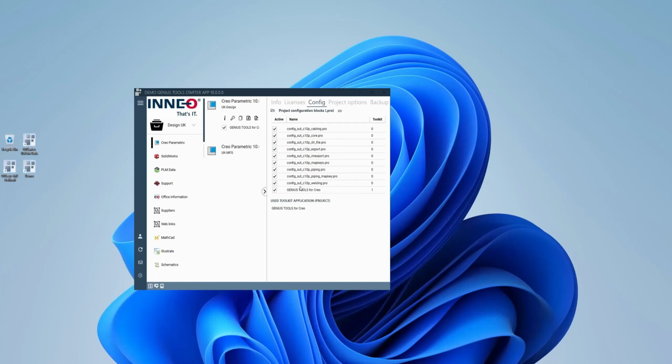Then when you look at your configuration command, so normally in Creo we'll have one config file, config.pro, and maybe a config.sub, but then you might have to create multiple copies of these files or this config file if you have people working on laptops or different locations. Maybe the one guy's working on the C drive, another guy's working on the D drive. So what we can do with this starter application is go and split the config file into multiple individual smaller config files. If you look at the second file on the list, it shows that there is one for all the core settings. So those might be the settings that will be the same for all the users, for all the different divisions that you want to use.